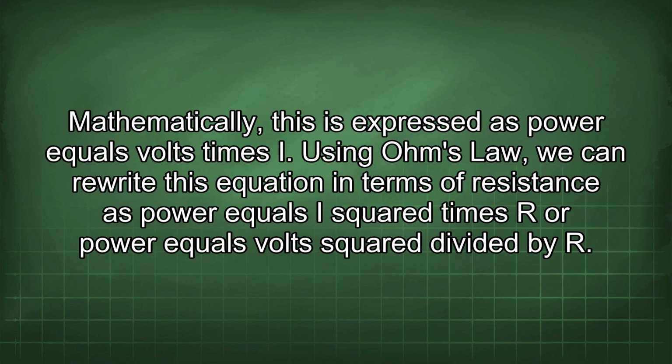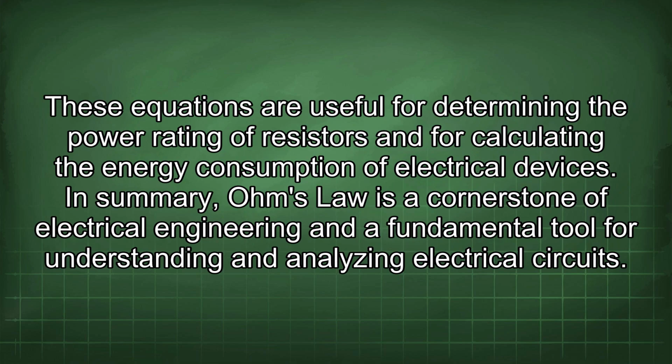Using Ohm's law, we can rewrite this equation in terms of resistance as power equals I squared times R, or power equals volts squared divided by R. These equations are useful for determining the power rating of resistors and for calculating the energy consumption of electrical devices.